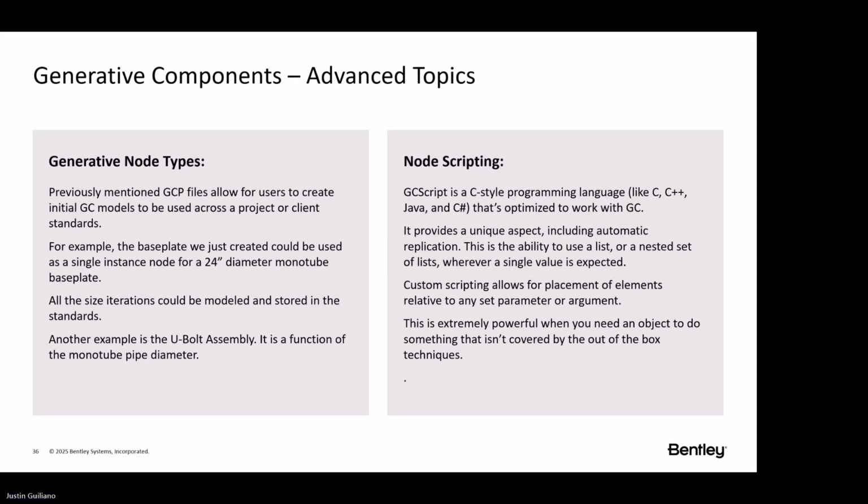It's really powerful when you get into some more intricate or detailed modeling, where it allows you to consolidate a lot of things. So for example, like the noise walls, I was able to take a script that had maybe 500 nodes and consolidate that down to half by utilizing a GC script that I could run for the different iterations or the different segments of the noise wall. So it's really powerful when you have an organized script. It allows you to consolidate stuff a lot more.